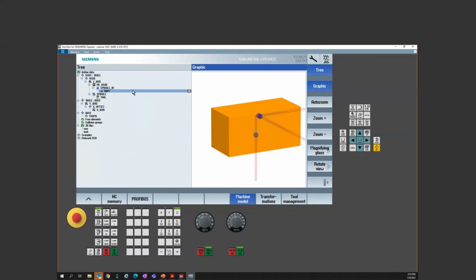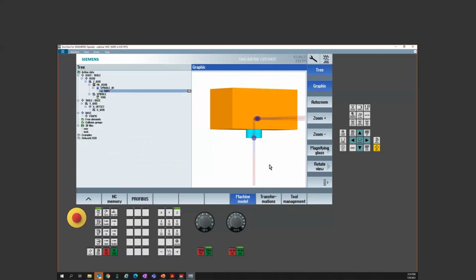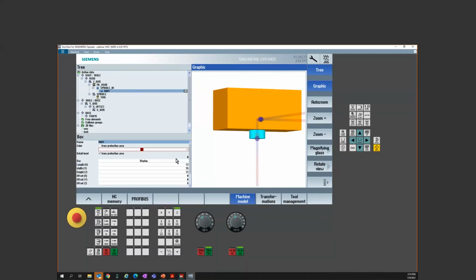I'll usually first try to shift some Z offset. So if I know this is 25, well then let me at least go 6, half of the object. So now I get to the point where, okay, well I got that, but I still need an extra 2.5 because of the additional spindle. So maybe I go